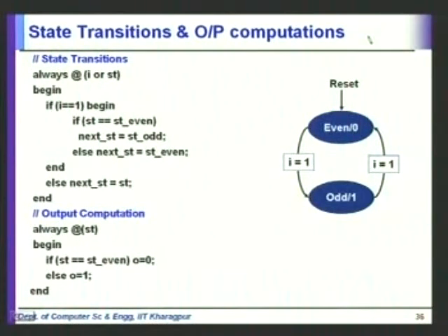So that is all that we have to do in Verilog. It's a brief overview of the different constructs in Verilog. We are going to look at different problems that come up from the syntax and the interpretation of the semantics of Verilog. One thing that we must be careful about are a set of static problems, like if you see that in the same simulation time, a variable is being assigned twice in the same simulation cycle.